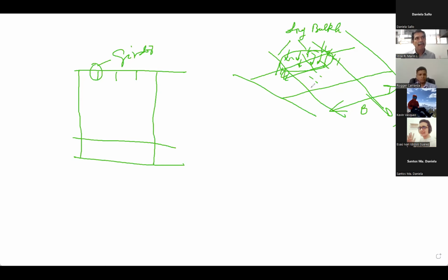Mr. Carranza? Yes, doctor. I confused the spacing of the girder on the longitudinal plan. Yeah. So this is the girder that you have to analyze. But you have to be careful, because if you have a longitudinal bulkhead until here, you can assume that the girder is clamped here and here.